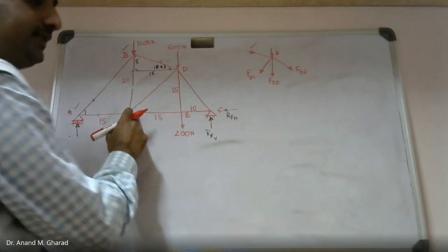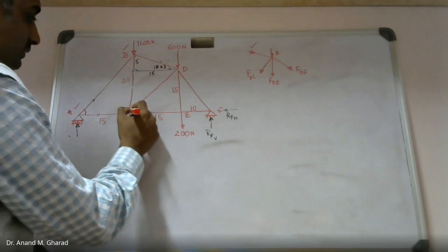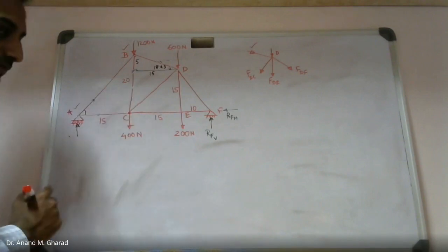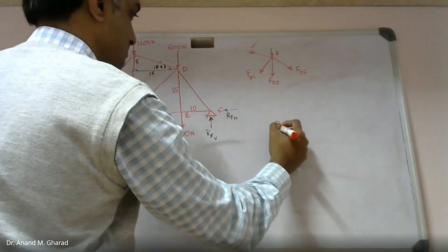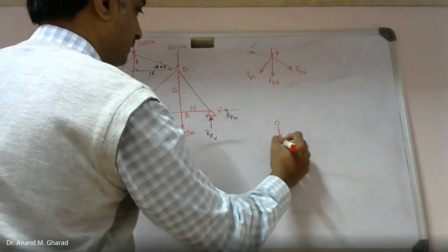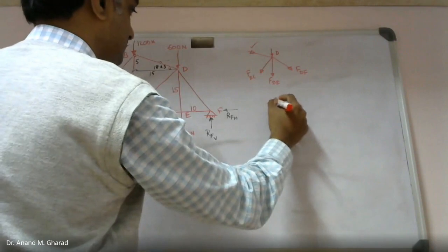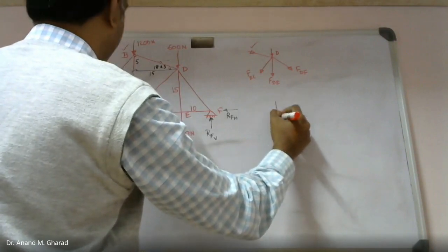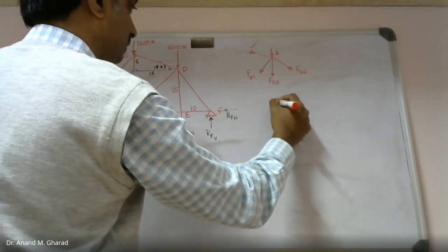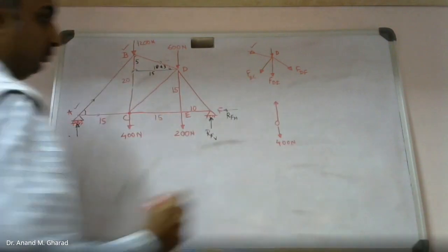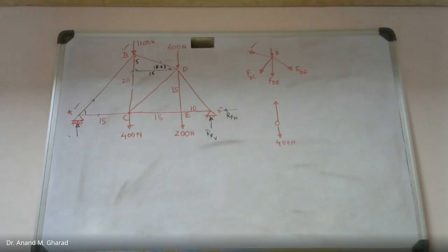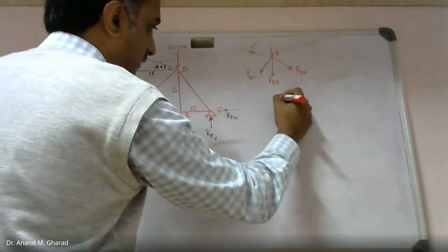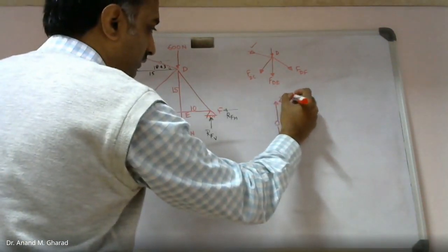Okay. Now, here I go. If I consider joint C, this is 400 Newton. This is the perpendicular member, which we have already found out. And this came out to be tension value, isn't it? Force in member BC, कितना था वो? Force in member BC 299.91 Newton.